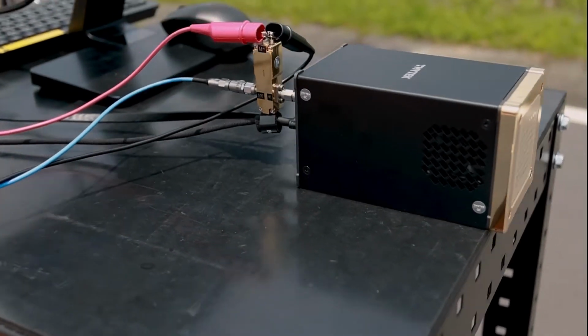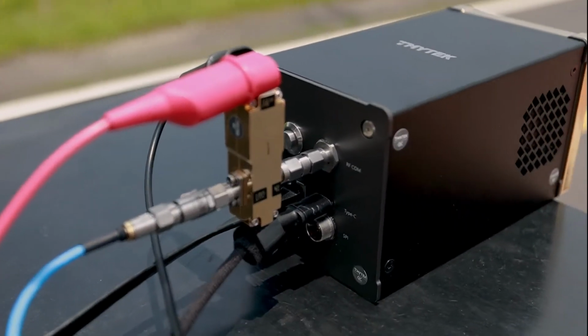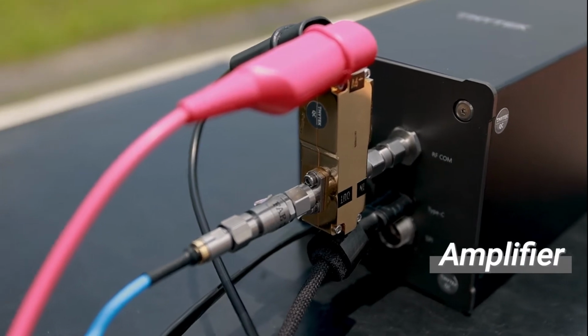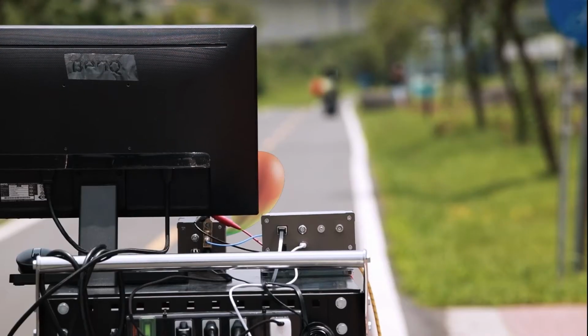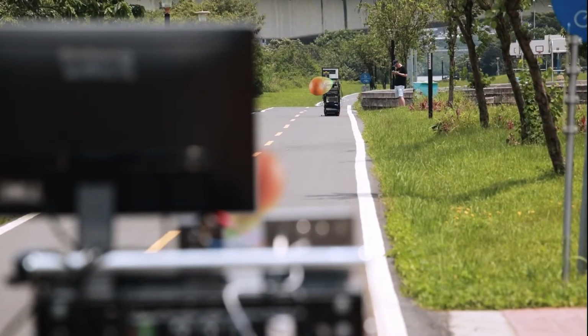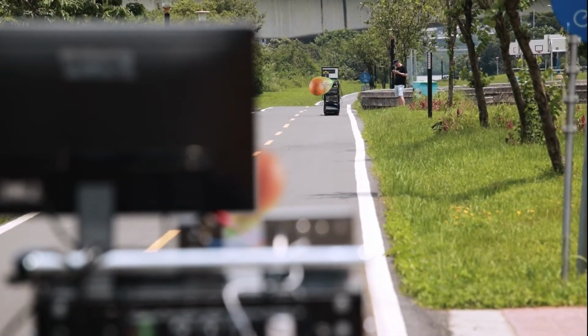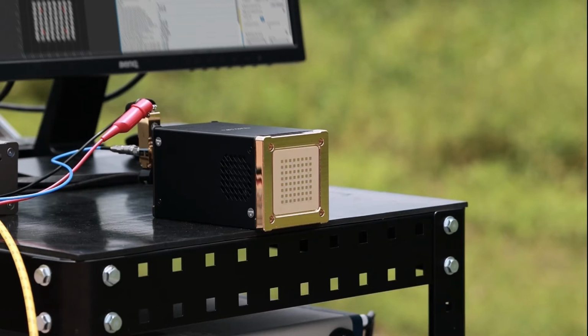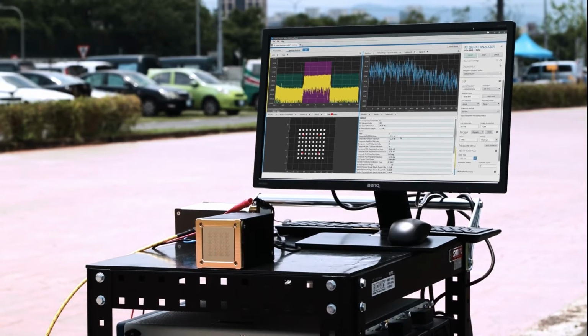In this case, we just use TMYTEK's amplifier between BBox and UD Box. Then we can adjust the beamforming direction for line of sight alignment and see if there is any improvement. Now, we can see the difference after beam adjustment. The EVM is better. The best performance is around -32 dB.